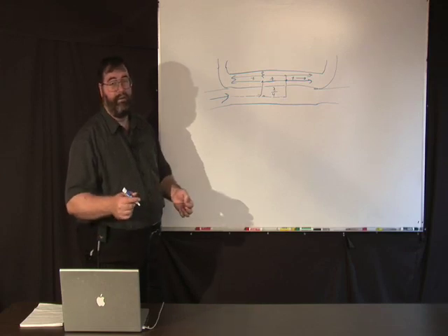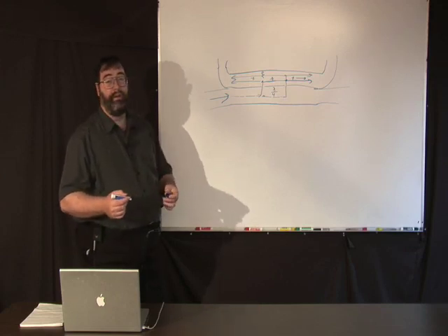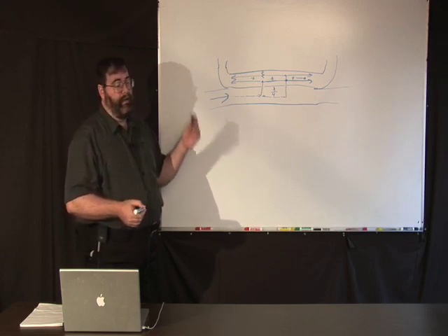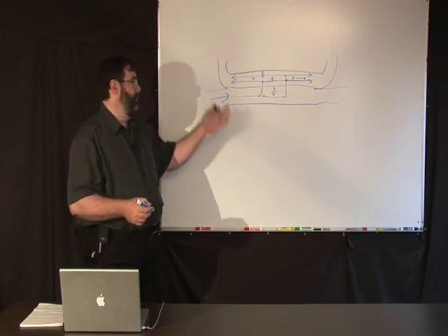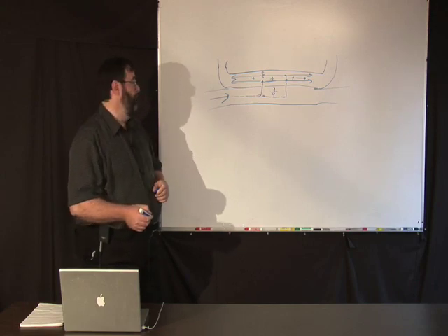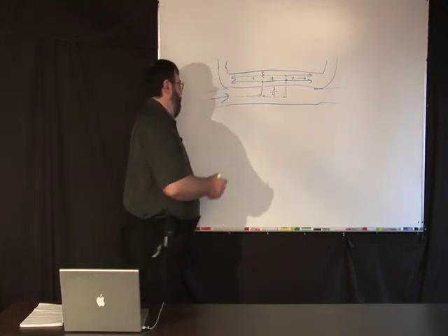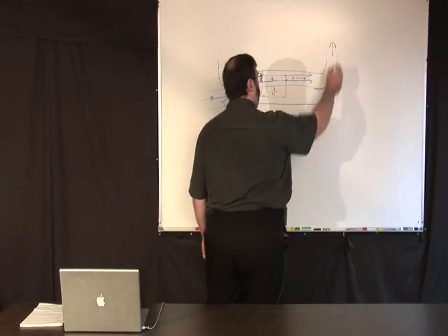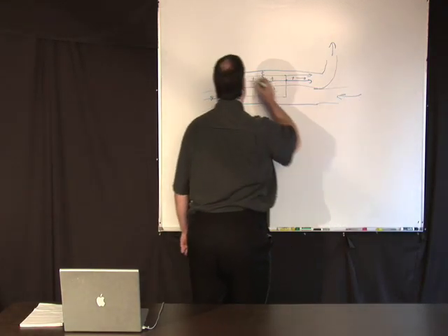There are all kinds of different directional couplers out there, but the main idea is in one direction, the signals will add, in the other directions, the phases will be arranged so that they cancel. So you have something that will, if you put in something at this port, it'll come out this port, and something come into this port, it'll come out this port.